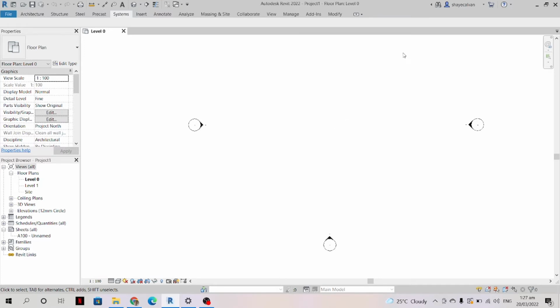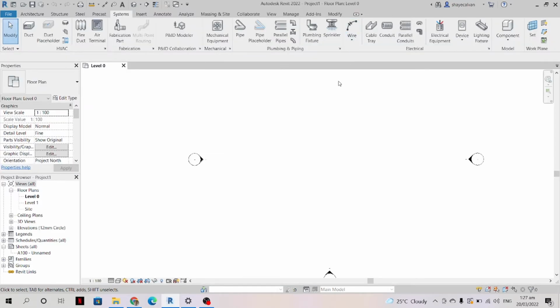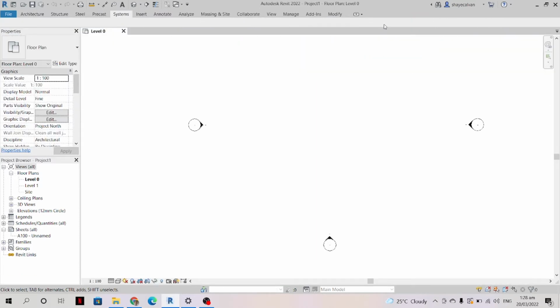And if I click this button again, the ribbon is restored back to the full ribbon. Notice that I can also click on the small arrow on the right of this button to display a shortcut menu. Here I can choose to minimize to tabs, minimize to panel titles, or minimize to panel buttons. If I enable one of these options, then clicking the ribbon state button toggles just between the full ribbon and the selected minimized ribbon. If I choose Cycle Through All, Revit reverts back to its default behavior for cycling through each ribbon state when I click the ribbon state button.